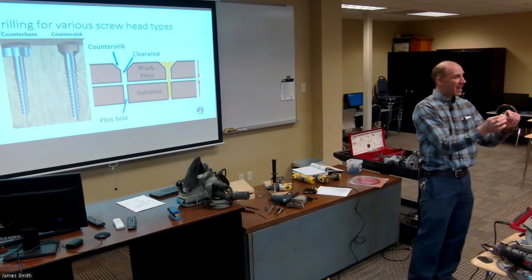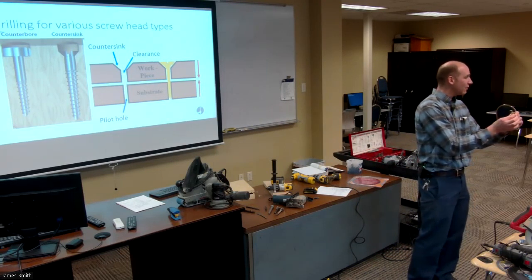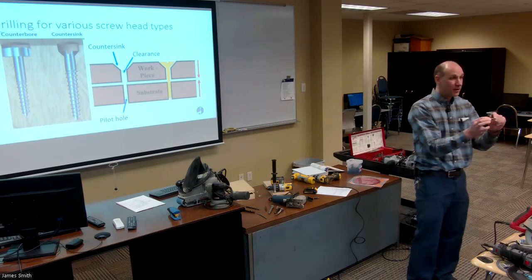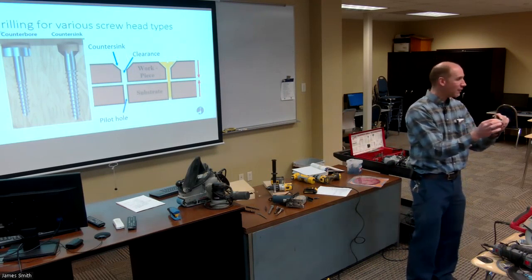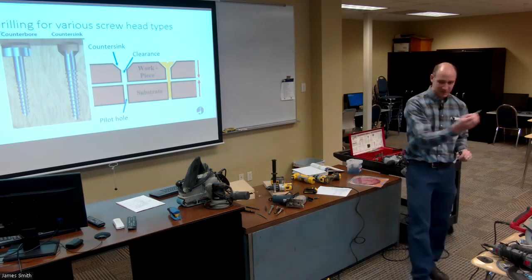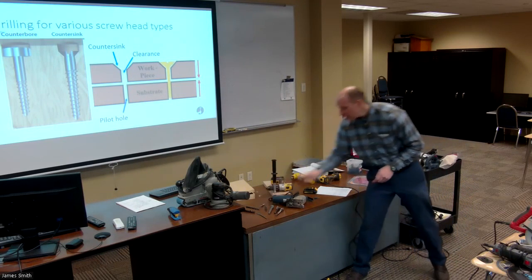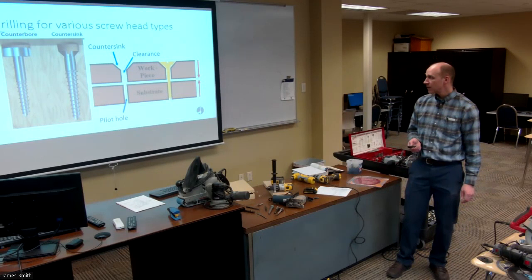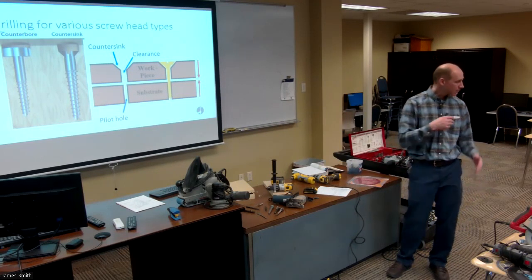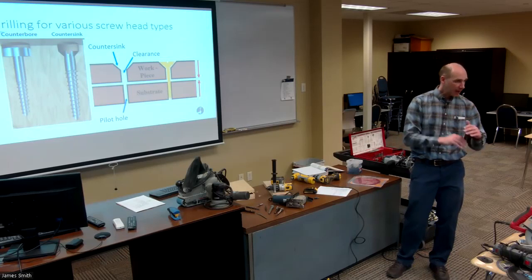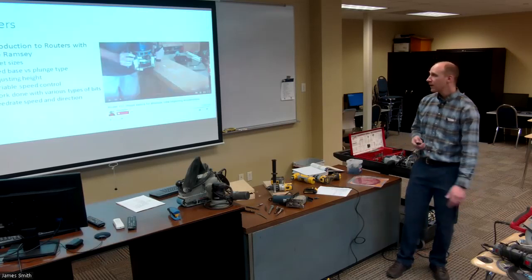And so the end of your bit is your pilot hole. The top of the bit is sized appropriately to be your clearance hole, and then you have your countersink and counterbore all in one bit. So it's a pretty nice little design, whoever invented that was really thinking. Okay, does that make sense? Pilot hole, clearance hole, counterbore, countersink. Okay.